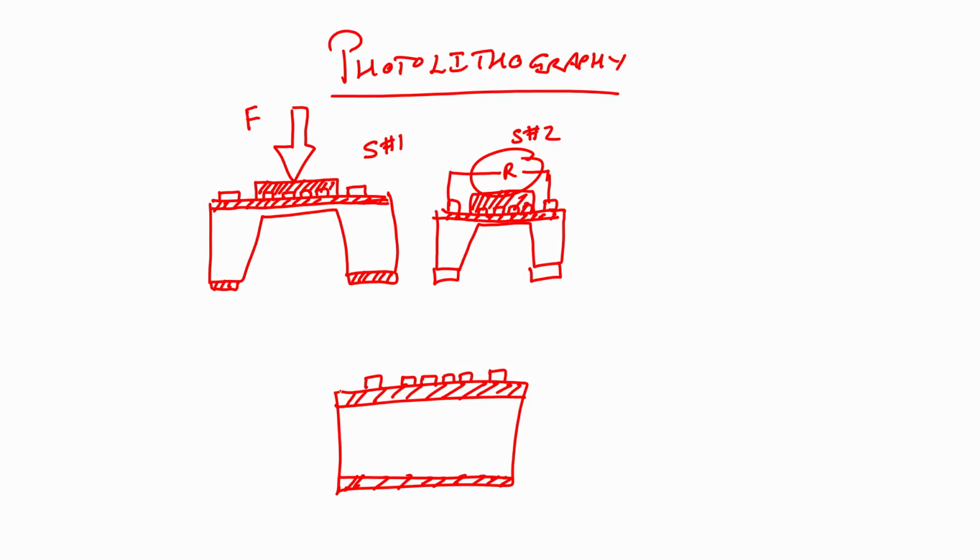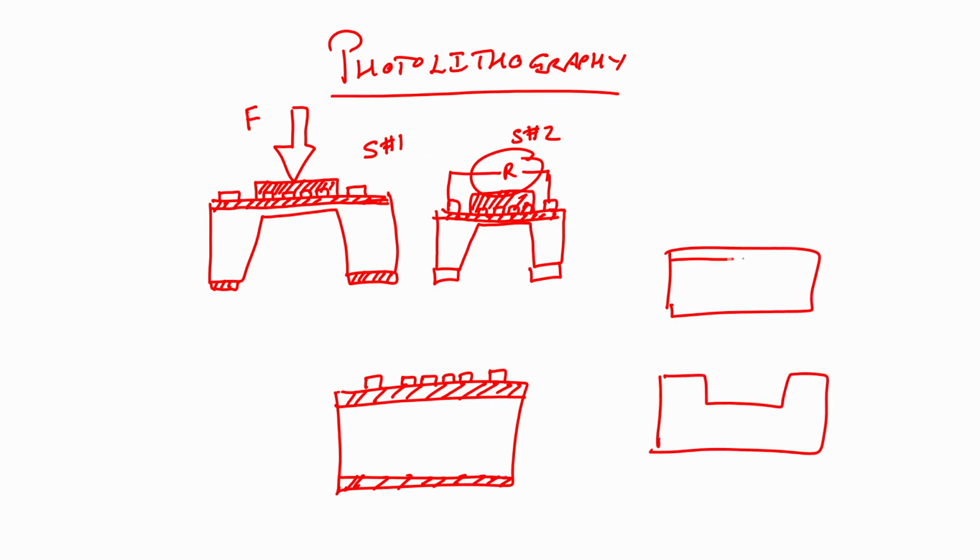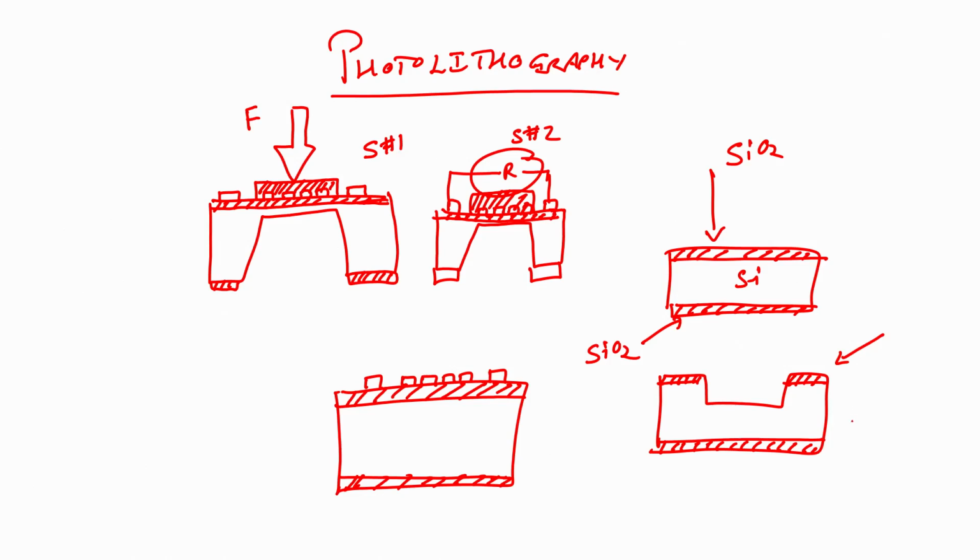After that, I will take another silicon wafer, an oxidized silicon wafer, and create a well like this. Now, why am I running faster? Because I am assuming that you now know very well what we are talking about in terms of microfabrication. How to create this well is very easy. Again, you open the window, etch silicon, and you get this mold. What I mean by open the window, etch silicon: suppose this is your SiO2, this is Si, this is SiO2. Now, if I want to get this particular pattern, what will I do?